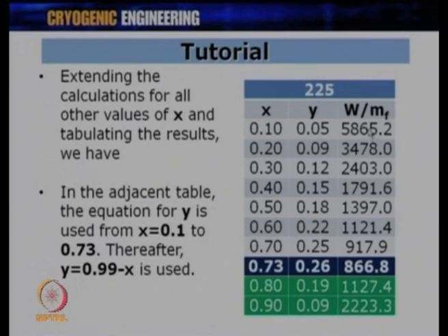That expansion engine, the amount of gas which goes to the expansion engine should be such that W by mf has to be minimum and y has to be maximum for that particular temperature T3. So, W by mf goes on reducing and it meets a minimum value at which y happens to be maximum, because W by mf is nothing but W by m upon y.